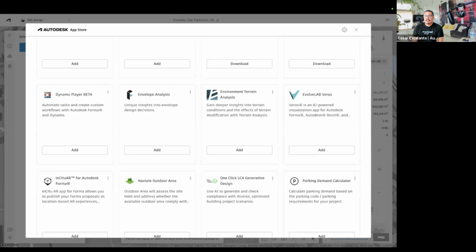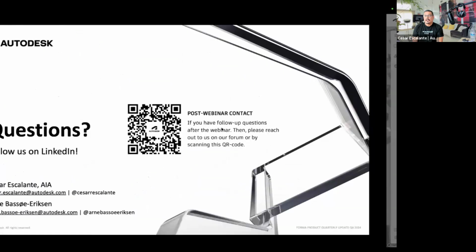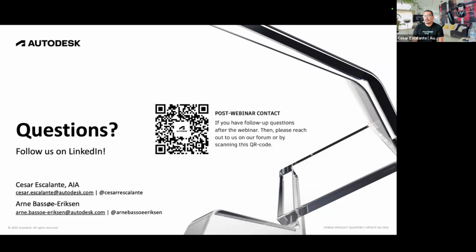But if you already have a project in Revit and you want to link a Forma site that is in a different shared coordinate system, you can create it in a blank project and then manually link it into your project. I know there are a lot of drawbacks in that process, but it's the immediate workaround. But expect expanded shared coordinate systems in the near future, and an improved workflow with shared coordinates.